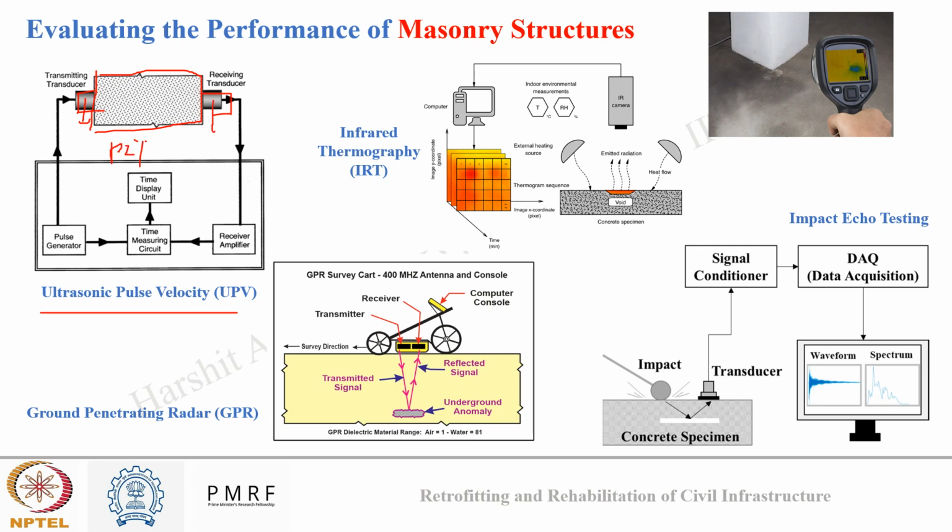Okay, what does a piezoelectric material do? It converts electrical signal into a mechanical signal, which can pass through the masonry, and once these signals pass through the masonry, the PZT again converts the mechanical signal into electrical signals, which can be read by us.